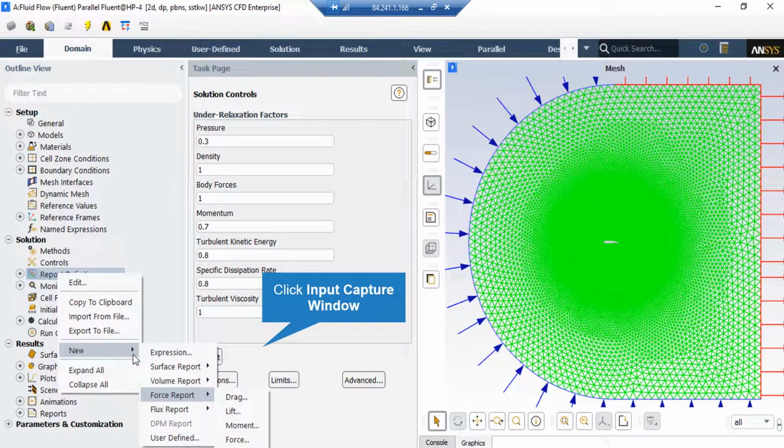There are two ways to check whether your simulation process has reached convergence. Alongside checking the residuals reaching and nearing zero, you may define an arbitrary report or arbitrary boundary in order to calculate different parameters like pressure, velocity, and temperature, and see whether they reach a constant value or not. If yes, it may be a sign that your simulation process has reached convergence.